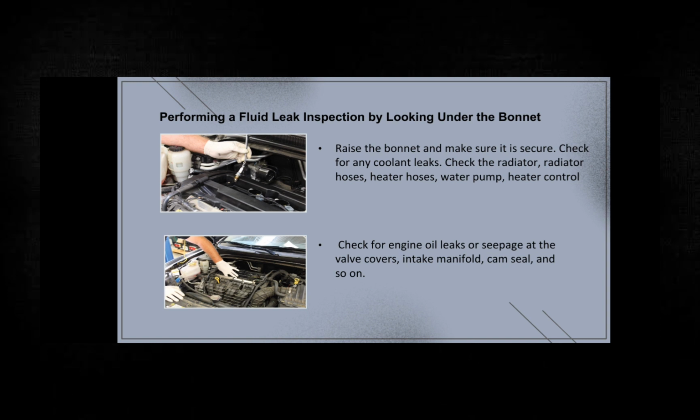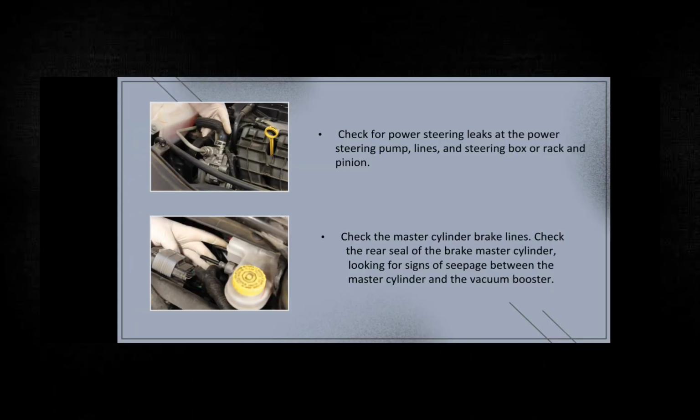Performing a fluid leak inspection by looking under the bonnet. First image, check for any coolant leaks. Check the radiator hoses, heater hoses, water pump, and heater control. Check for engine oil leaks or seepage at the valve covers, intake manifold, cam seal, and so on.